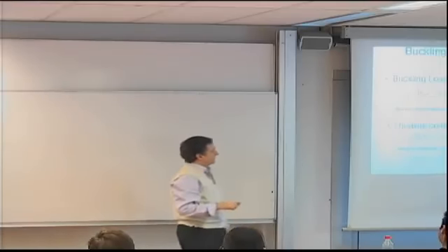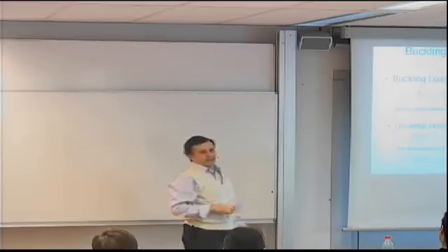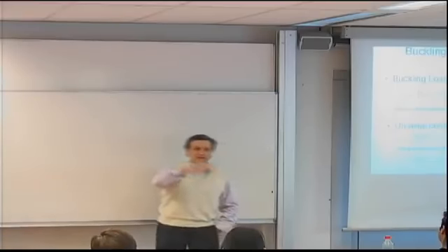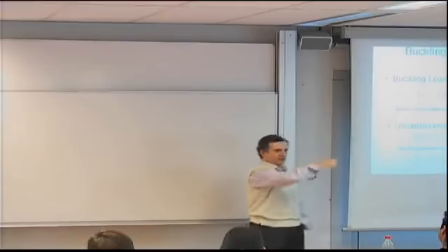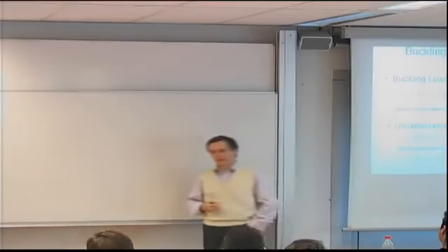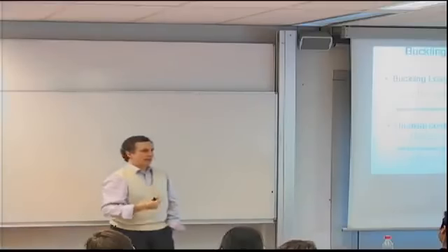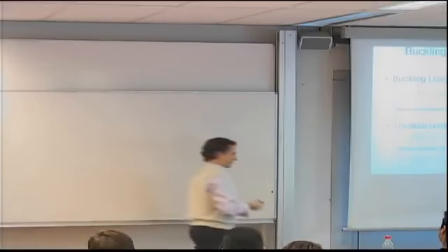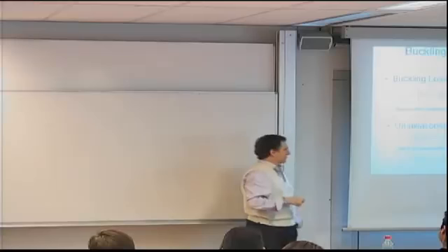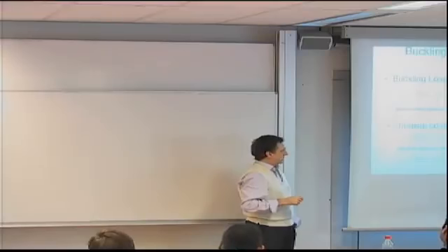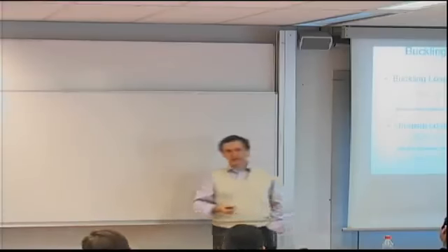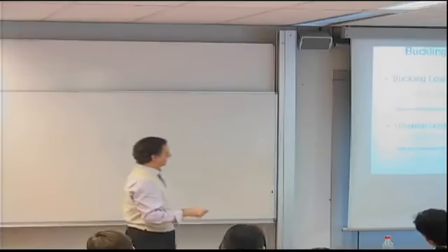And now this quantity is a function of m and n, and as I was saying last time, m is the number of half waves along the length, n is the number of half waves transverse to the length or along the width of the plate. And we have to find the values of both m and n for which this is minimized. It's easy to do that for the case of n, because n appears only in the numerator. Therefore, the lowest value of n is the one that will minimize it, because all the terms in the numerator are positive.